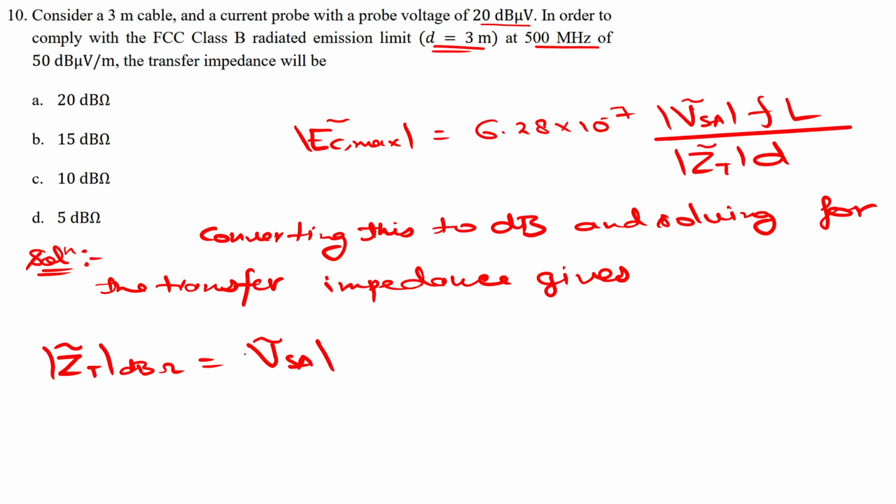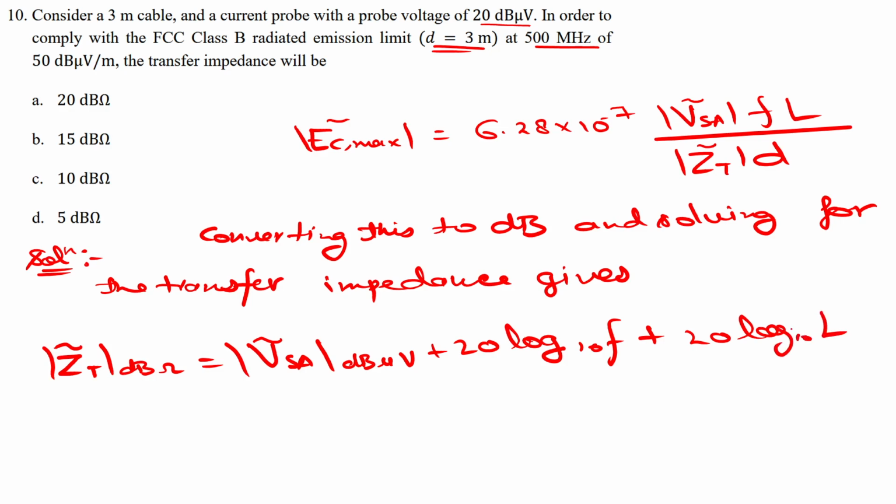the voltage reading from the spectrum analyzer, which will be in dB microvolt, plus 20 log base 10 of frequency, plus 20 log base 10 of length.